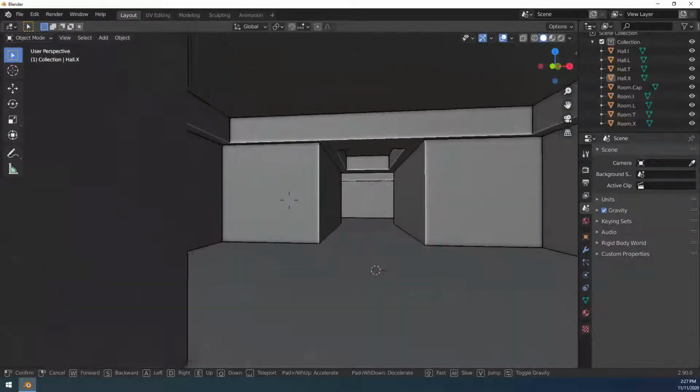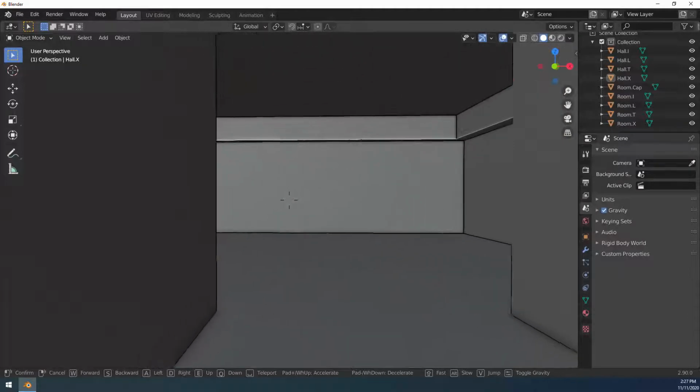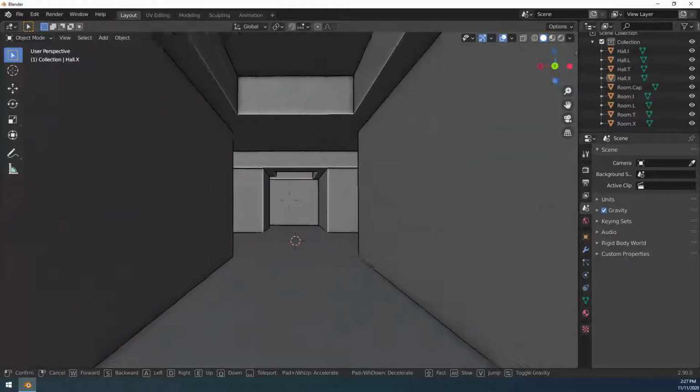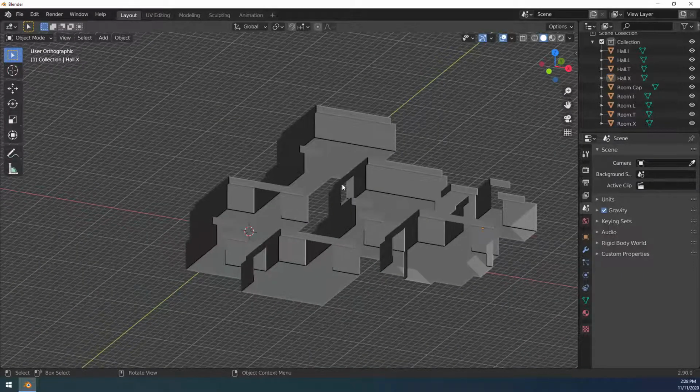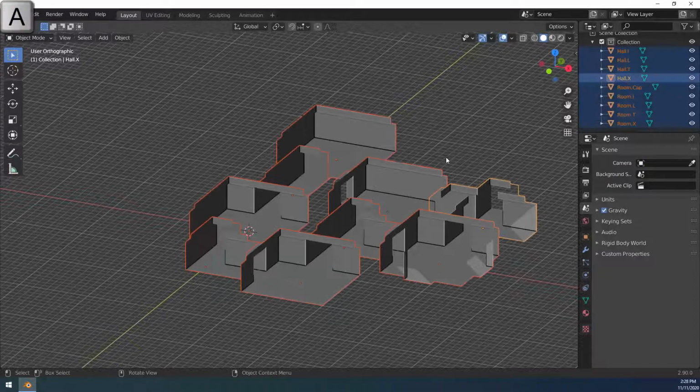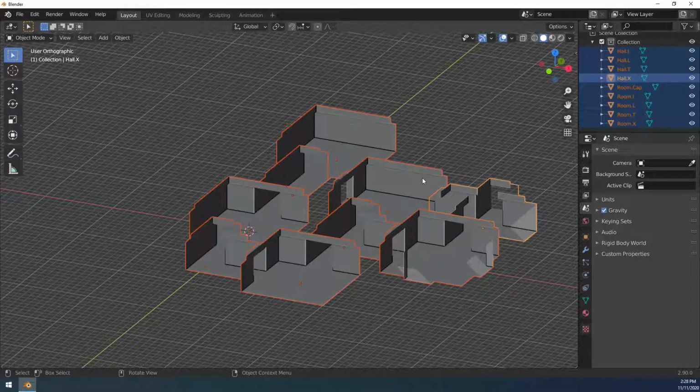Now, this is a lot of information, and I think you guys should go in here and practice this. Next week, I'm going to be adding to this. We're going to extend upon this and make more interesting dungeons. If you want to put all of this stuff back, I'll go ahead and select all. So we've relocated a lot of these, and we've also rotated these. So to restore the rotations and location information, we can use Alt-G for the location and Alt-R to reset the rotations.